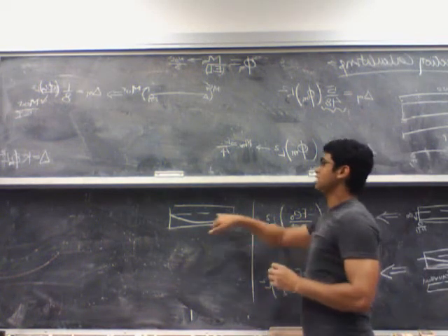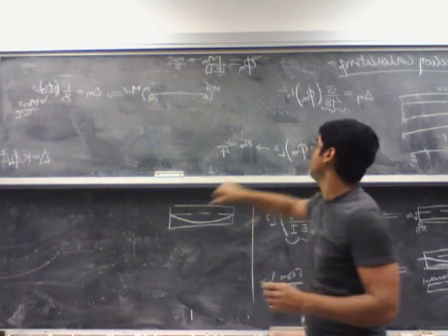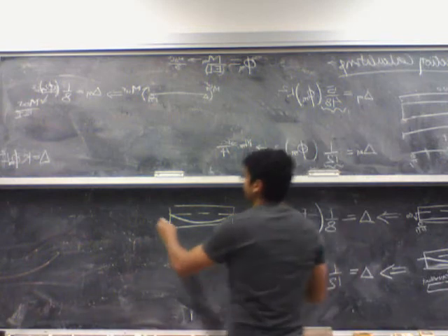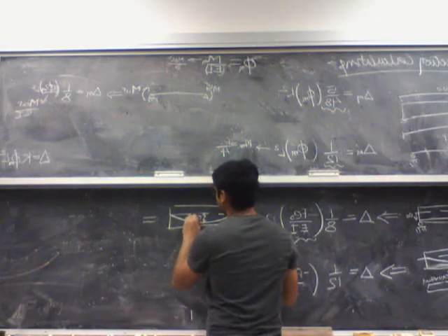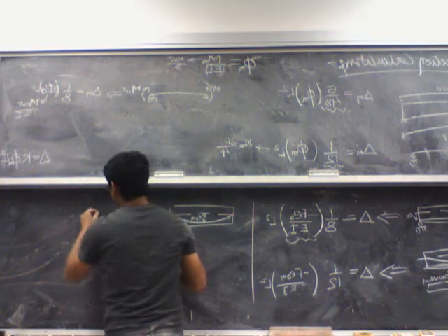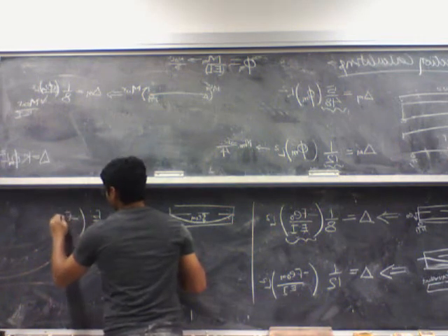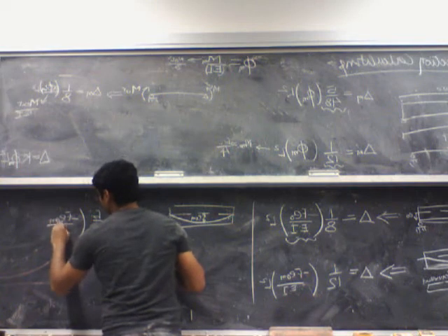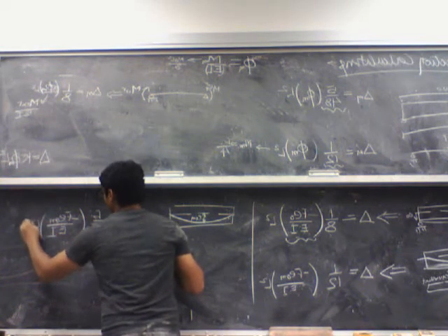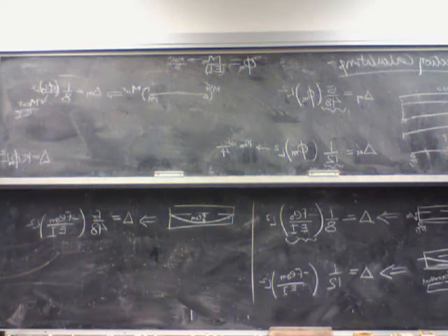Right? So in case of parabolic tendon, the equivalent load for a parabolic tendon is a distributed load, same as this. So I can directly go ahead and, let's say at the midspan again it's e naught m. So in this case my delta is simply given as 5/48, again F e naught m over EI L square. So for these three simple cases, what I am simply trying to do is for each case I am trying to relate it to an equivalent case where you actually have an external load.